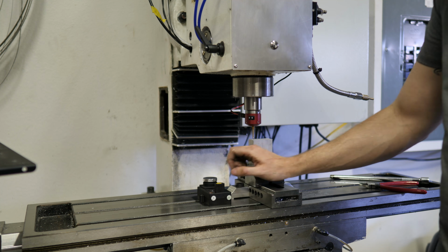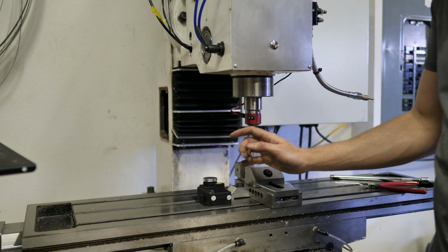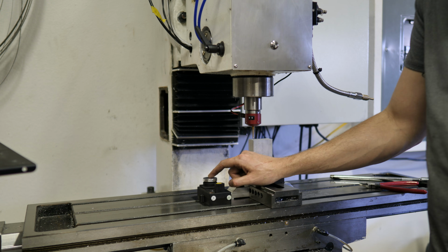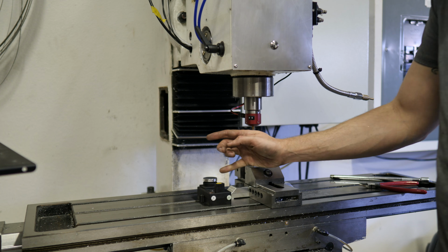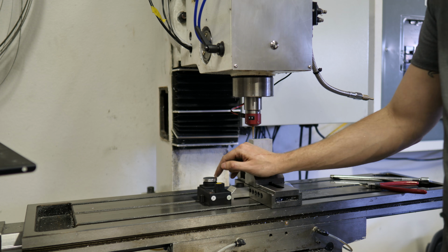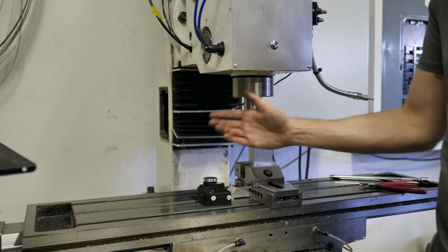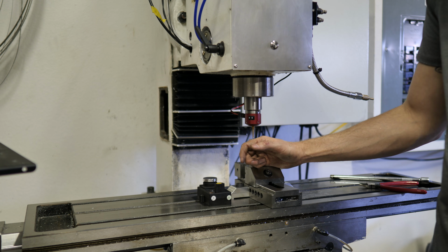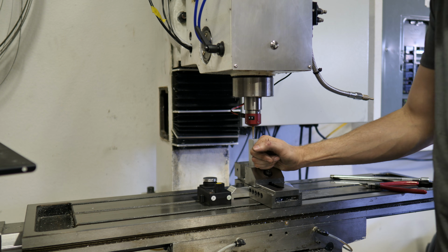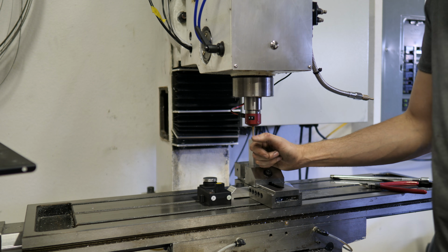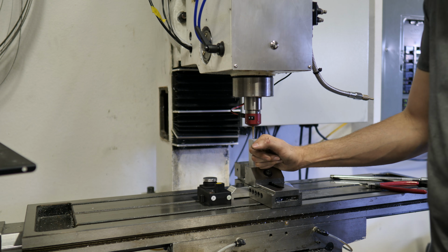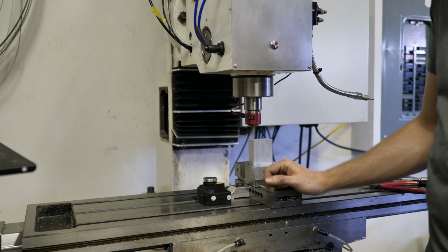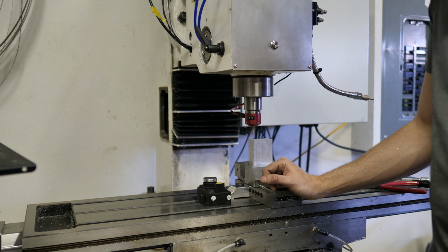And that'll come down and probe it same way it probes Z, except instead of telling the machine it's at 0 on the Z axis, it figures out the difference between that Z0 and what it just measured and spits that out as the tool height. And it will automatically populate your tool table with whatever tool you have selected and that tool height. So it's pretty automatic. I can run through 24 tools in 5 or 10 minutes. Pretty handy. Other than that stupid thing where I've got to change the pin number on the probe.